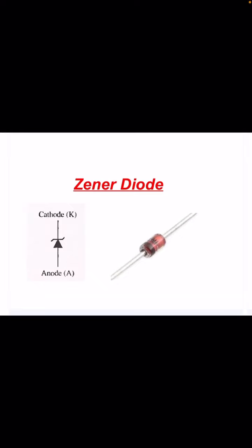And we discussed the characteristics and especially IV characteristics, and we saw that there is a non-linear relationship between the current and voltage for a diode, which is also known as non-ohmic device. So we have two types of device, linear and non-linear, or we can say ohmic or non-ohmic. Those which follow the Ohm's law are called ohmic, and those which don't follow, meaning the graph between I and V is non-linear, are known as non-ohmic devices. So a diode is a non-linear or non-ohmic device.